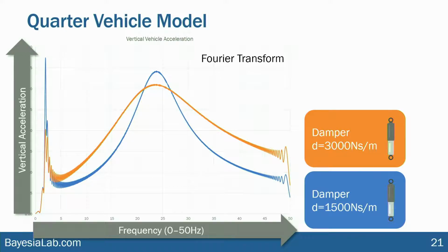Okay. So now let's perhaps choose a firmer damper setting. And with such a firmer damper setting, we see a significant attenuation at the peaks. But as a trade-off, other ranges have increased. Now, what that means in practice isn't so important for our exercise. However, you can imagine that engineers must make trade-offs in terms of what is more important.